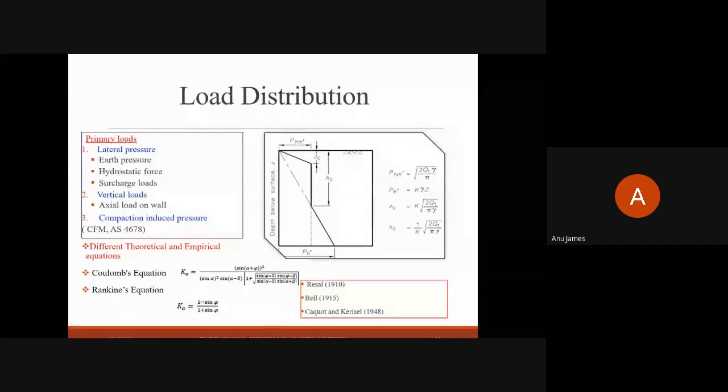In the design of normal retaining walls, the skin friction components are generally ignored. But for a diaphragm wall system, due to its larger ground interaction area, this skin friction component need not be ignored. So we need to consider the axial load from that part.